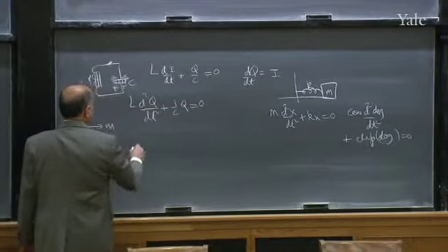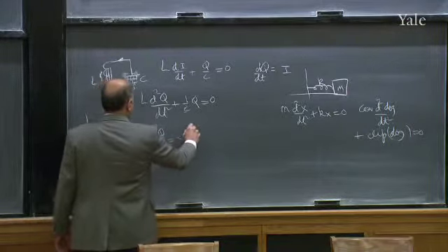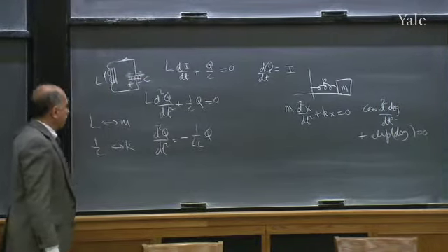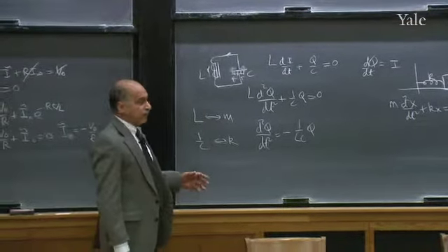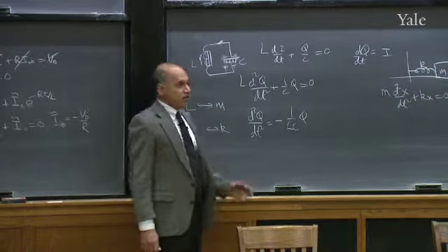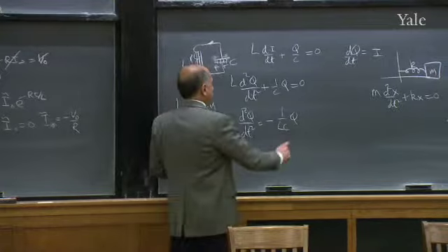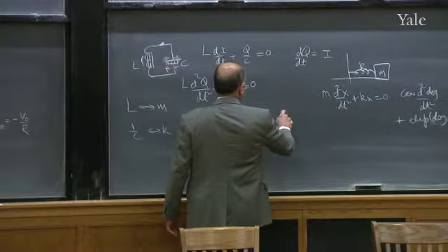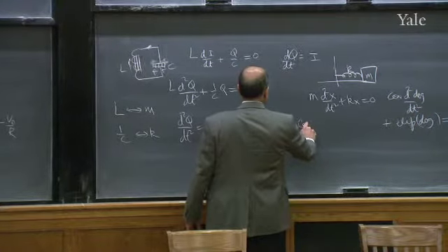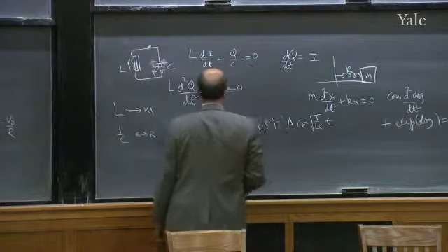So what's the answer to this one? Once again, it's a differential equation. You write d²q/dt² is minus 1 over LC times q, and you're asking yourself, give me a function which, when I differentiate twice, looks like itself. There's always the exponential. There's also sines and cosines, and you can take any combination you like, and one acceptable solution is some constant a times cosine of the square root of 1 over LC times t.